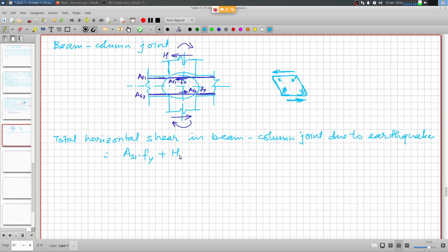And this is done by continuing the transverse reinforcement in the beam column junction in the case of reinforced concrete structures. In the case of steel structures, special details are required to ensure that this panel zone doesn't buckle under this massive compression, and that is often the cause of failure of steel buildings.